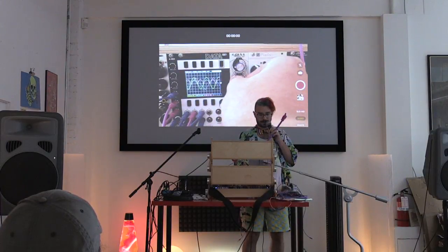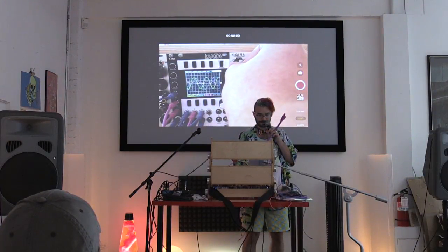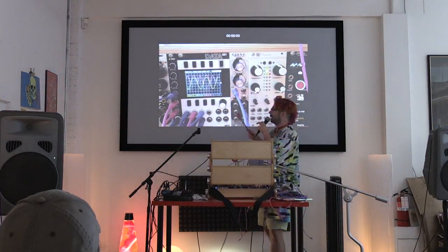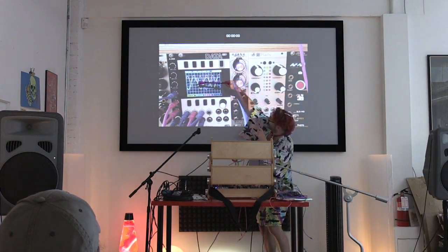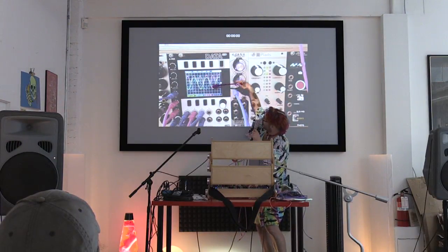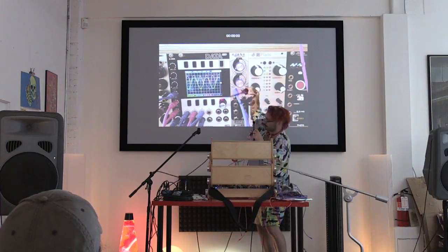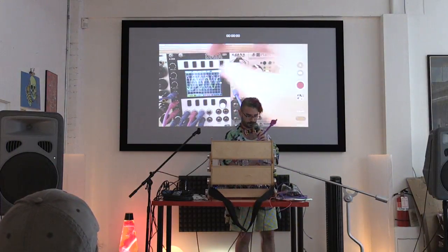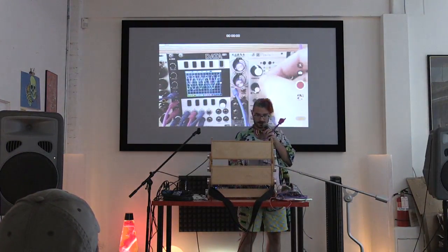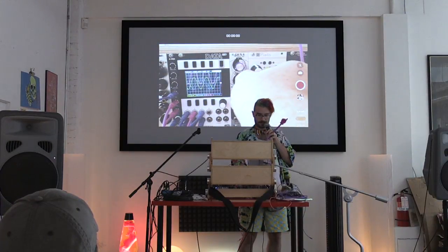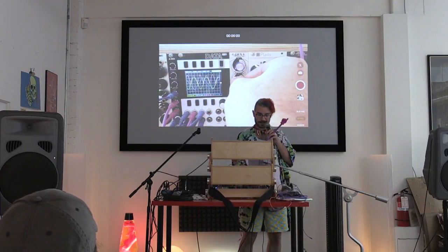So if we subtract two signals and take the rectified version of it, you're ending up with something that's actually like an octave up. So we've got our sine wave coming in, and you can see this bouncy sine wave going at twice the speed of the input. So if we listen to that, you can hear this interesting octave doubling effect, right around there.